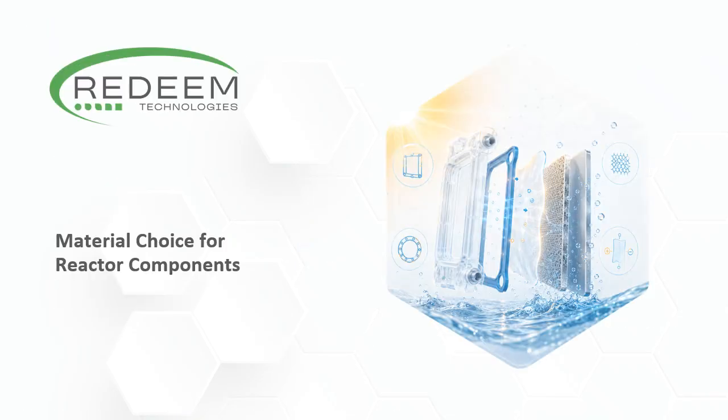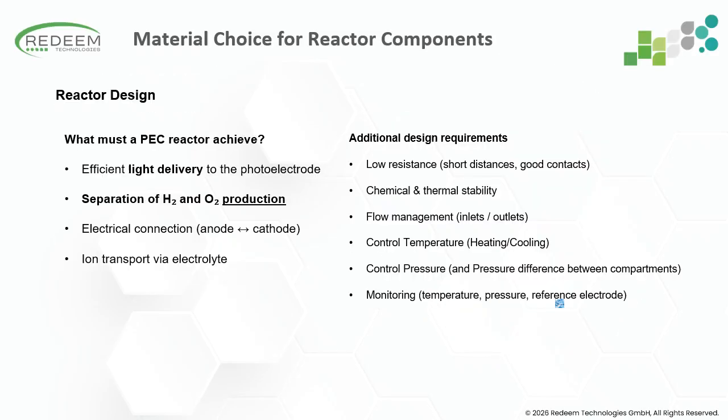So the performance of a photoelectrochemical reactor depends not only on the photoelectrode itself, but also on the materials used throughout the entire system. So in this chapter, we are looking at the key considerations when selecting materials for the different reactor components. At its core, every PEC reactor has to perform several tasks simultaneously. It has to efficiently deliver light to the photoelectrode, provide a pathway for electrons to go through an external circuit, sometimes it's internal, transport ions through the electrolyte or membrane, and generate hydrogen and oxygen in separate compartments.